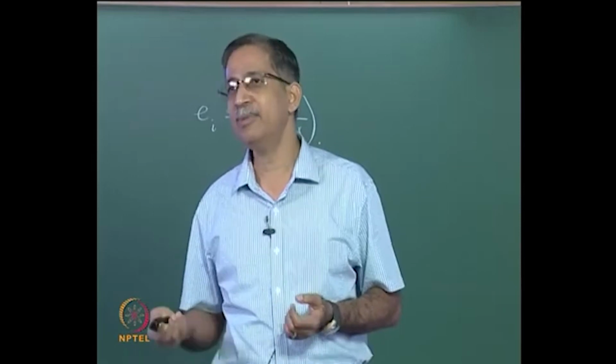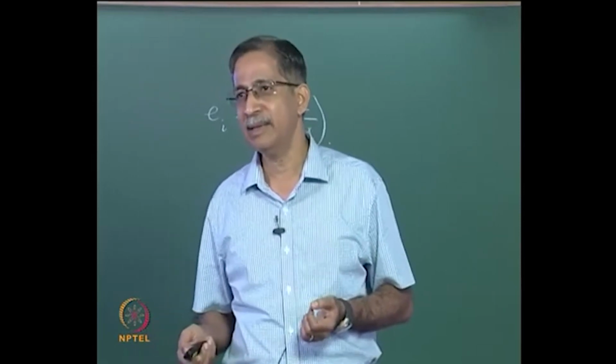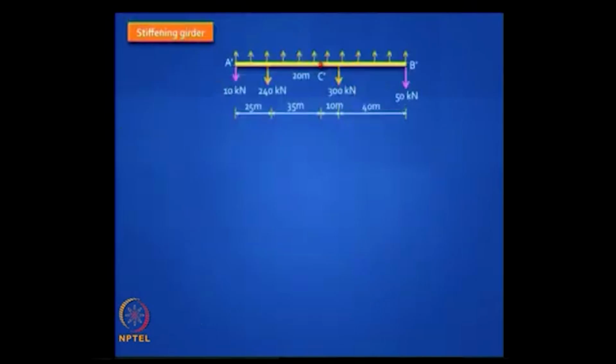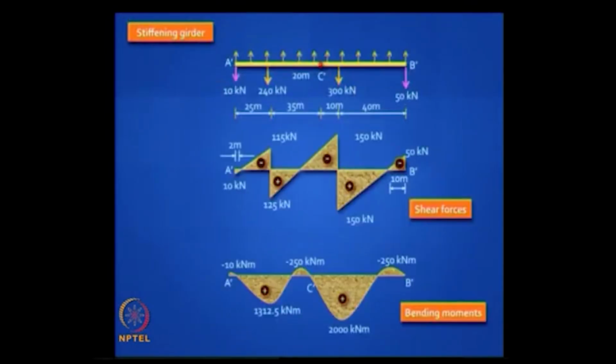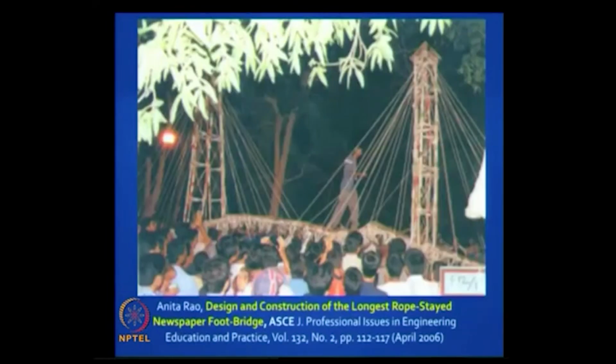Now in this problem you can work this out, you can get the results, and once you separate out the stiffening girder, then you can work out, it is statically determinate. If you cut any section, you can work out the shear force and bending moment diagrams.